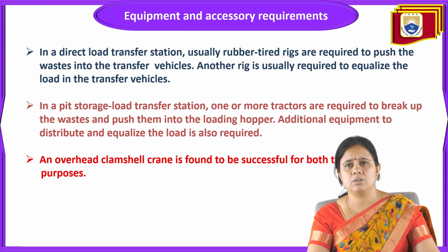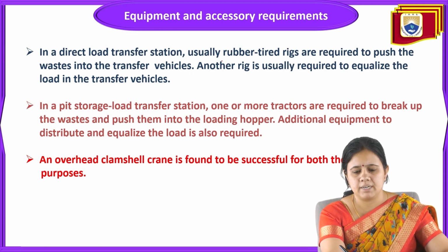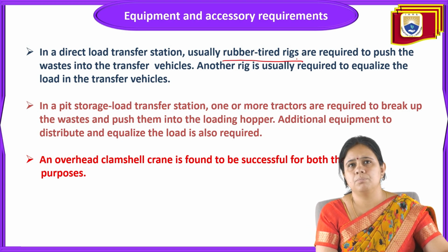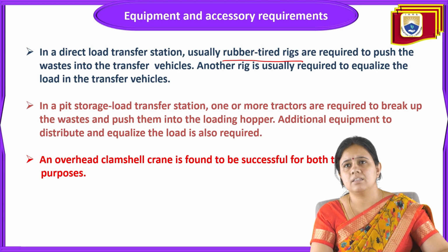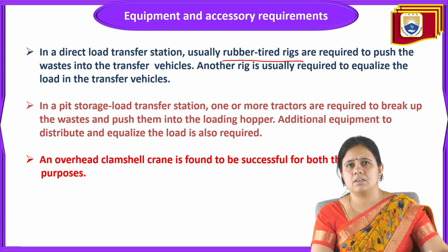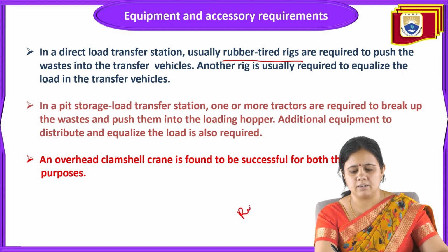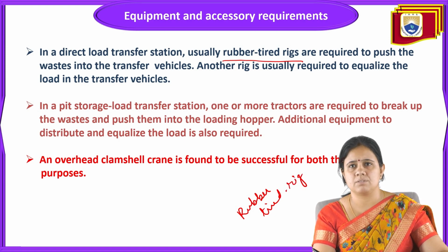In a direct load transfer station, rubber tired rigs are usually required to push the waste into the transfer vehicles. Another rig is usually required to equalize the load in the transfer vehicle. And in a pit storage load transfer station, one or more tractors are required to break up the waste and push it into the loading hopper.